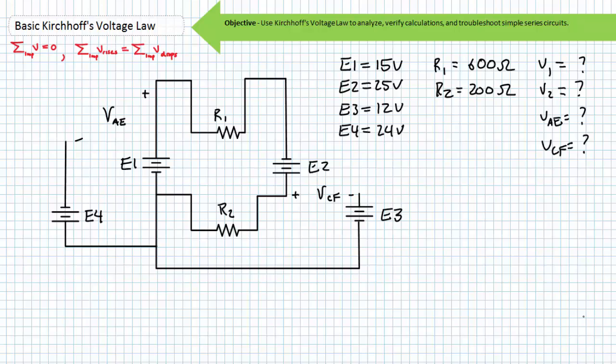To top it off, the textbook typically has the wrong answer in the back. Still, this is just a simple KVL problem, and if you look at it correctly, you'll find it's a series aiding configuration. It may help to redraw this monstrosity in a more reasonable fashion.